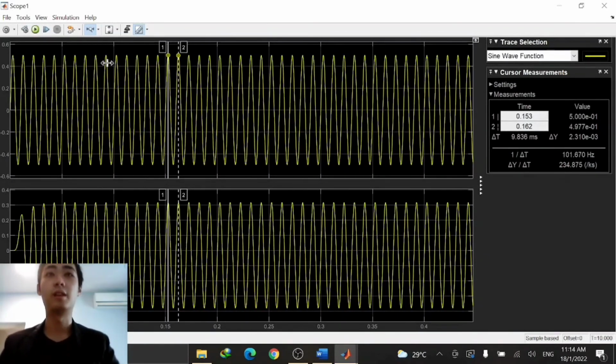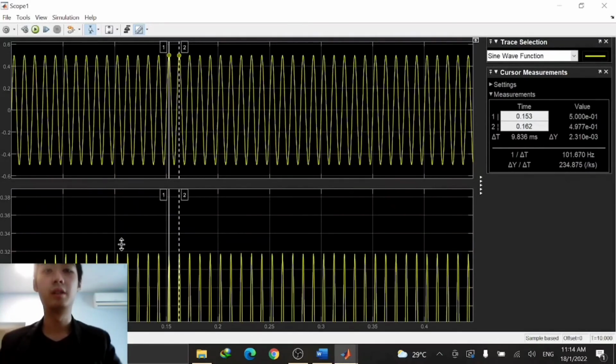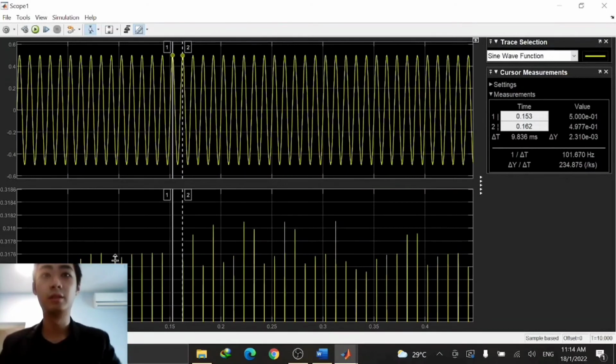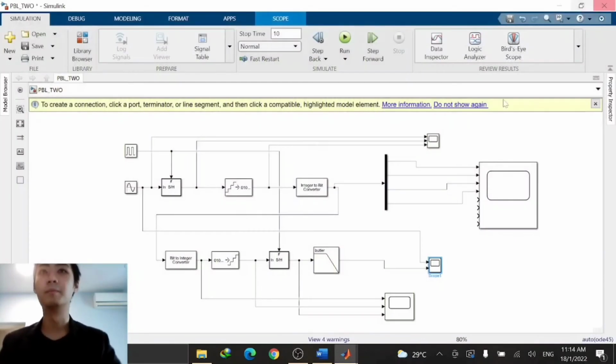There is an initial delay, but the amplitude of the output is lower than the 8 bits and more inconsistent. The average is around 0.3176, while the 8 bits has more consistent amplitude or oscillations, and the amplitude is higher than for the 4 bits encoded PCM.